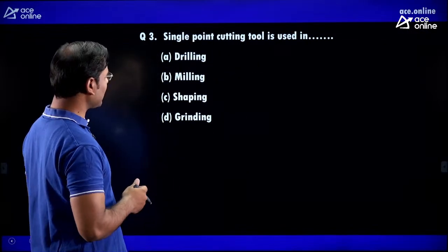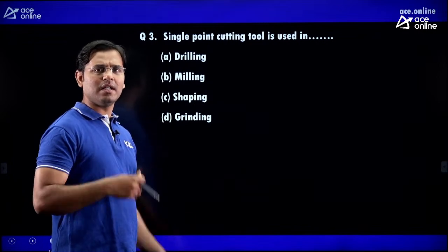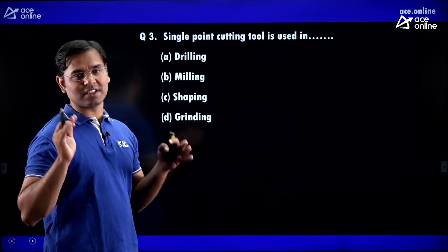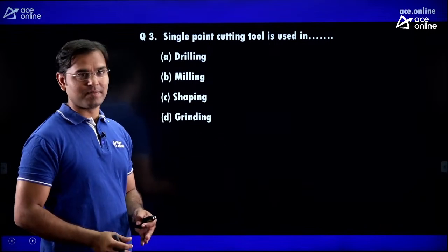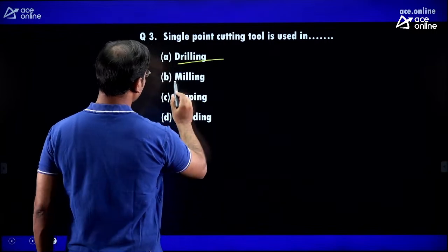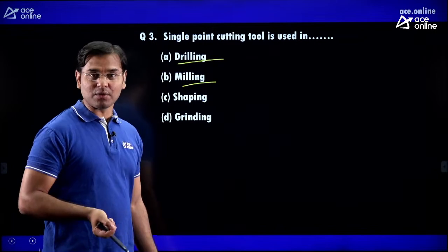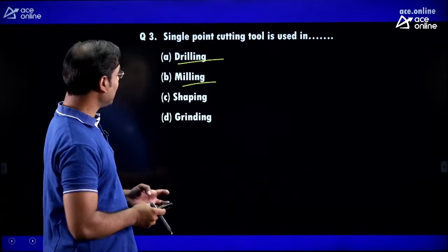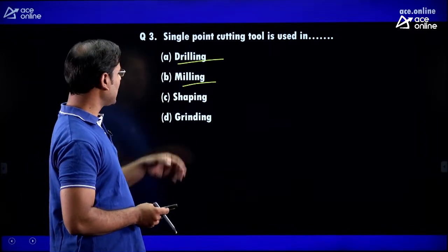Next, single point cutting tool used. Now it is a tough question, because drilling, milling, shaping, grinding, all people say are multi-point cutting tools. Wrong. Drilling is a multi-point cutting tool. Milling is a multi-point cutting tool. But in drilling, a number of single point cutting tools are there, and when we combine all those single point cutting tools, we get the multi-point cutting tool in drilling.